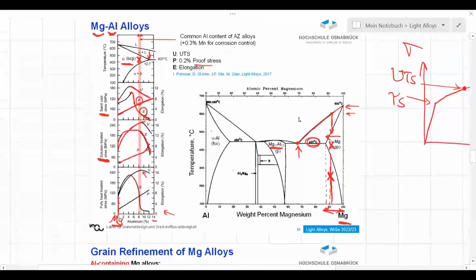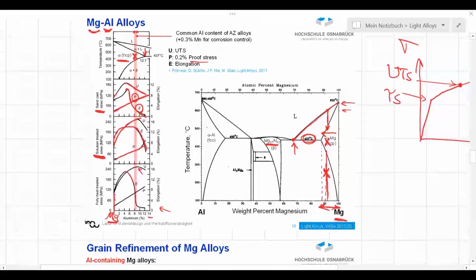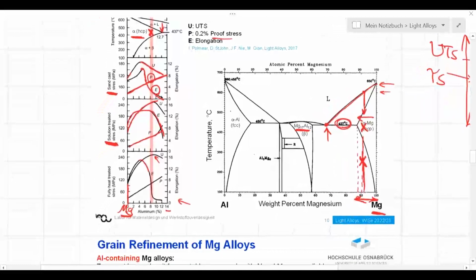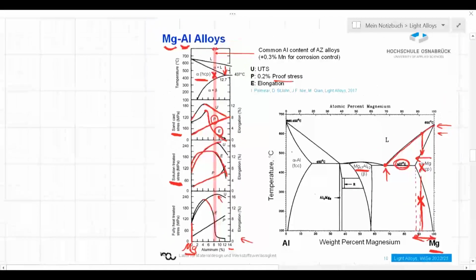Good. Now, one of the things about this alloy system, it looks like an attractive system to do precipitation hardening, but in reality, it is not attractive. In the context of aluminum alloys, we were saying that we could do heat treatment in the single phase alpha region, and alpha in the context of aluminum is FCC solid solution, then rapid quenching and heating up again. For example, in the aluminum copper system, let me make it a bit bigger.